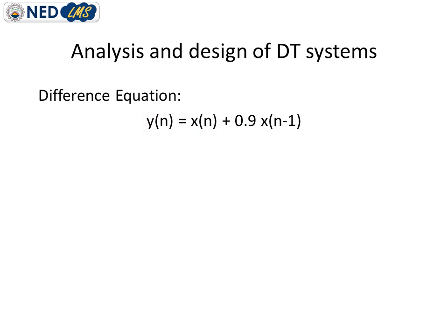First thing we can tell by looking at this difference equation is that the input and output sequence must be discrete, because here the x and y variables are depending upon the n variable, which is representing a discrete time system. So input and output sequence must be discrete. Another thing we can tell by looking at the difference equation is its nature. It is a finite impulse response system.